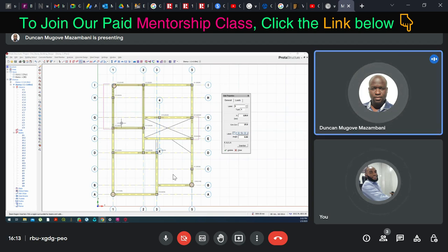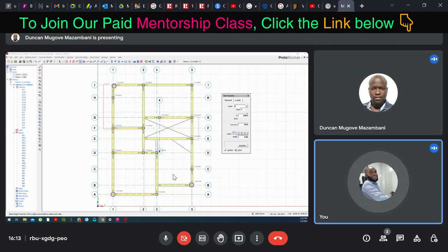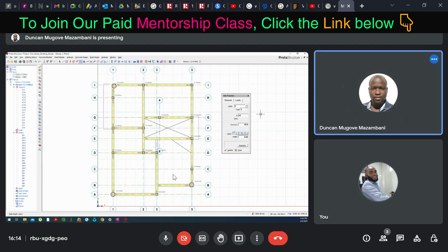Can you hear me? Yeah. Choose your slab thickness. Minimum should be 150. Although most countries like the US use 120 as their minimum, the BS code specifies that your minimum depth of slab should be 150 millimeter. So the place where you have H 120 should be 150.